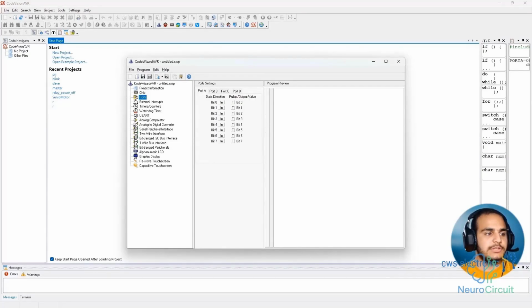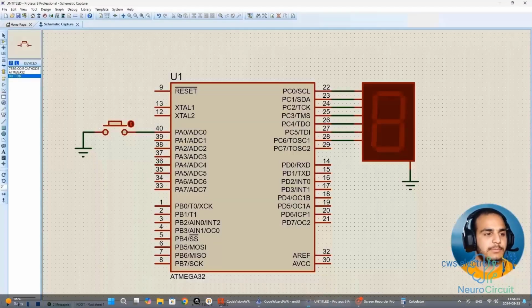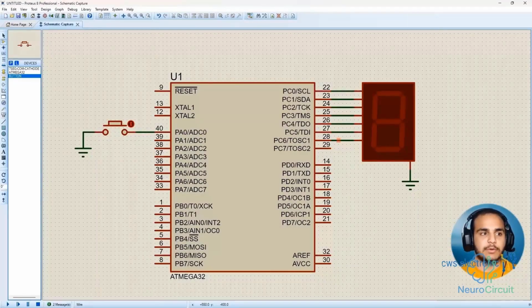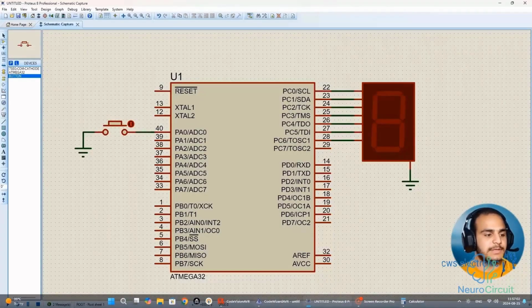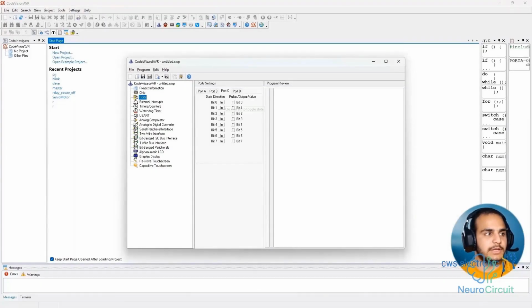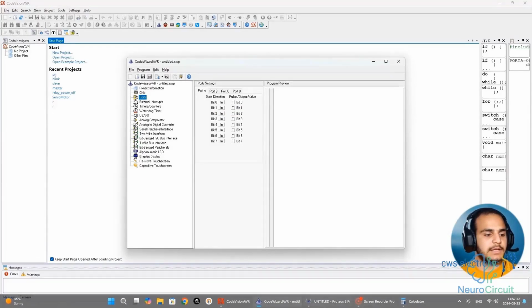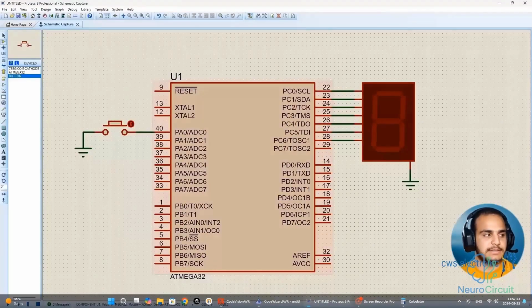In the port section, this particular time, we are utilizing port C, and we are going to make use of 7 of its available pins. The 8th pin in this specific configuration does not need to be explicitly set as an output, so we are setting 7 of the pins belonging to port C as outputs. And on the other side, bit 0 of our port A is directly connected to the button and consequently should be set as an input.